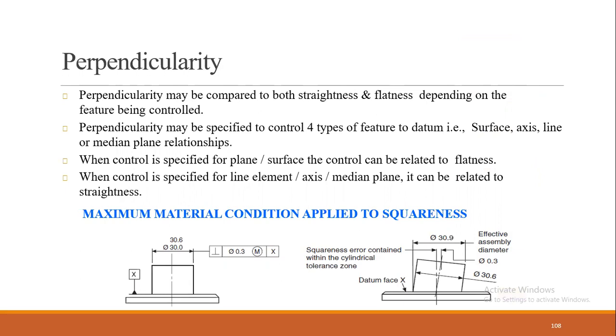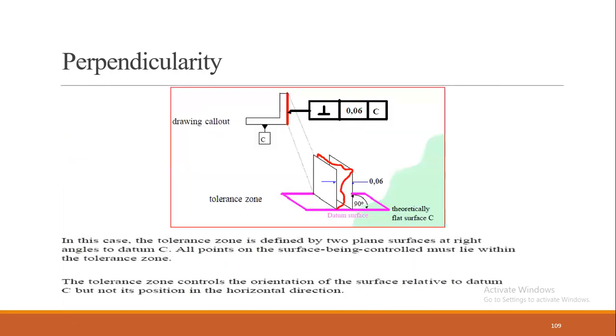If you get some tilted angle or distance, if you create a center line from the center of the part, and I create a straight line from another second point, and the gap between them is more than 0.3, then it's not acceptable. If the gap is less than 0.2, then it's acceptable. So this is the use.